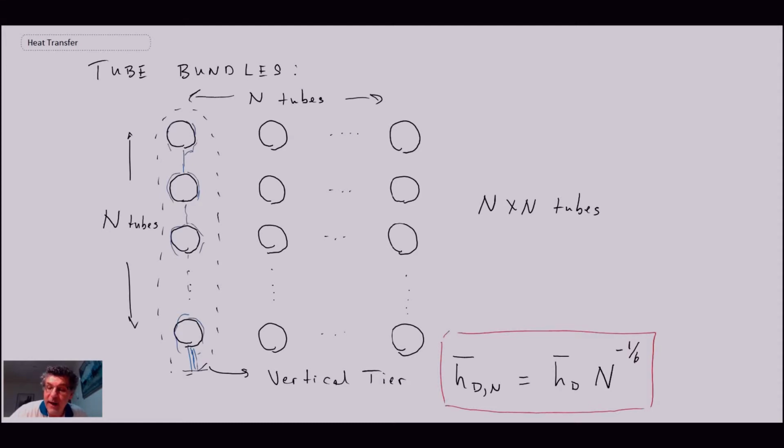And essentially what happens here is the convective heat transfer coefficient is going to drop down somewhat. And the reason for that is if you think about the fact that as you get more and more condensate or condensed liquid forming around the outside of each of these tubes, that then provides a bit of an insulating layer, and consequently we would expect that the amount of heat transfer, convective heat transfer, is going to be reduced as you get a larger and larger film forming around the tubes.